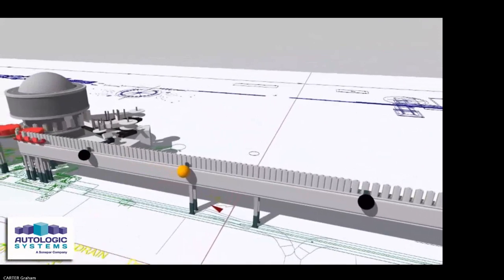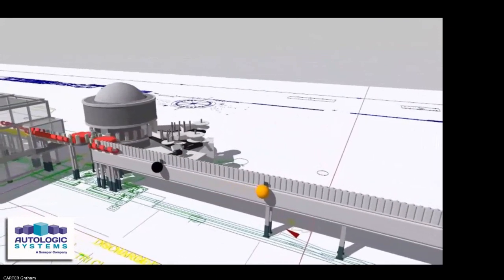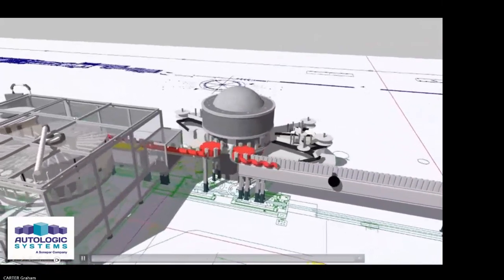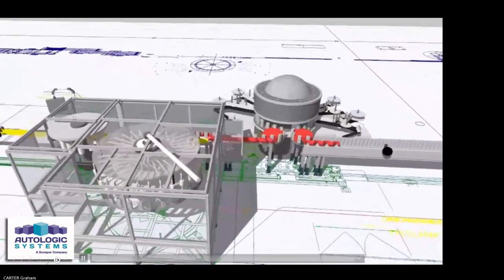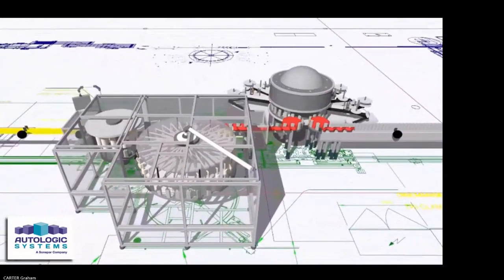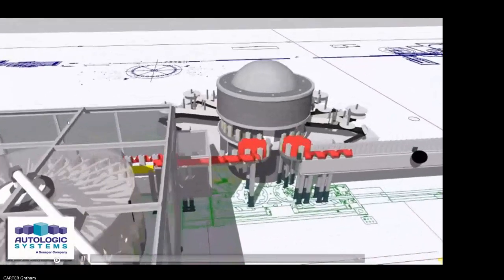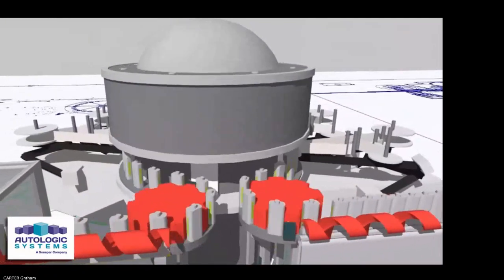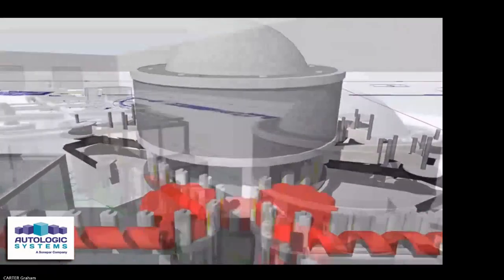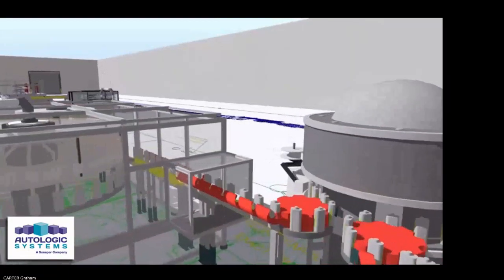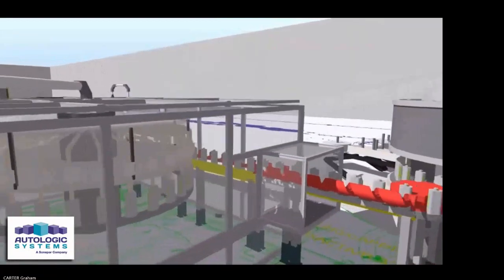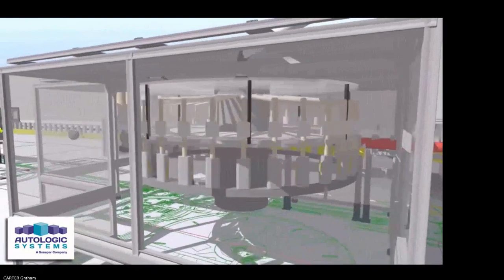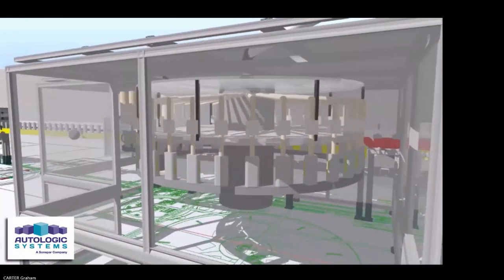This is showing it not in the physics world in this particular case, but if we have the physics world engaged, then the center of gravity of our bottles and the weight and the resultant coefficient of frictions all come into play. But between our processes, it's all conveyor, and that acts as the buffer. And how we control the variable speed of those drives and the position of our sensors are all there to gain and improve our OEE, the truly productive time, avoiding, what do we do when we're blocked, the best way to handle it, how do we keep the upstream running, how do we avoid starvation between our 5 or 6 connected processes here.